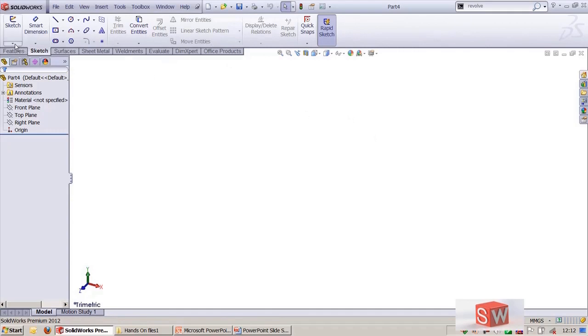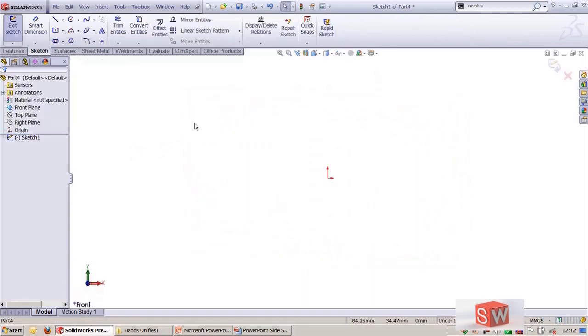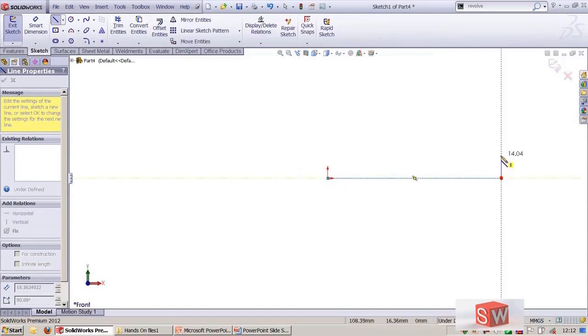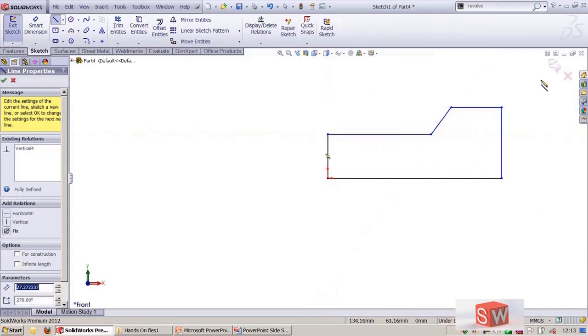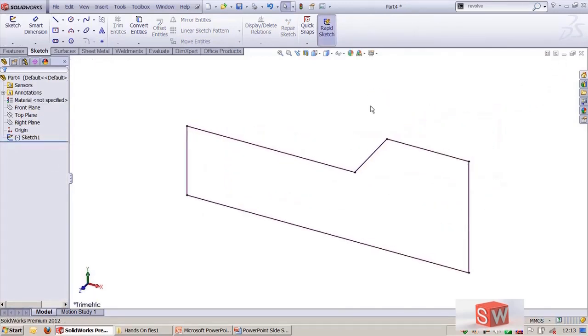Go to the sketch tab. Here I have sketch, and I need to select a plane, and you can choose any entity from here to create a closed loop or any open loop. This is one process of creating a 2D sketch. Once you create this, I can use the confirmation corner to end this process, and the next step is I would like to create a 3D sketch.